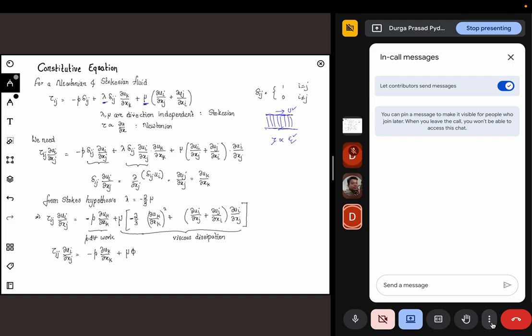So what we are doing with this constitutive equation is reducing the problem: instead of measuring two quantities, we are doing it in a different way. We'll measure only the strain rate, basically only the velocity, and then the fluid property will help you find the stress. Since we are fixing the relation like tau equal to mu times du dy, you only measure the velocity profile. From that you can calculate the derivative and, with the fluid property, calculate tau in a scenario where you do not have access to measure it directly.